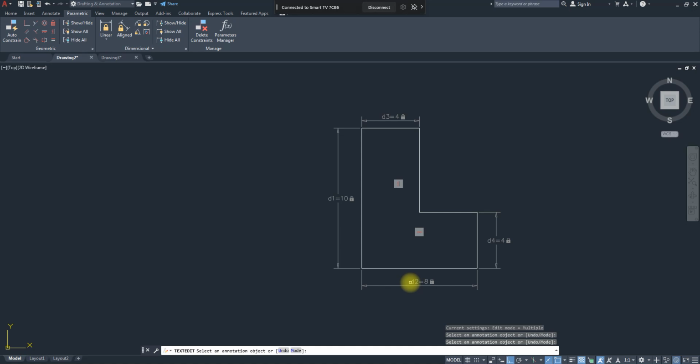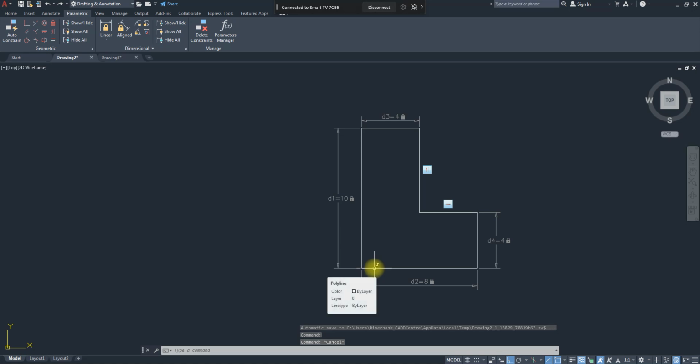Fixed point that you talked about, it maintained it. Remember when creating this? Scaling up. Okay. No, no, no, no. It depends on the constraint you add. The constraint I added was just dimensional constraint. So that means if I add dimensional constraint, I can change the length. So I can just change this 2 to 4 and it will be fatter than that one.